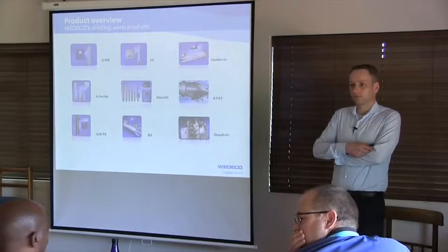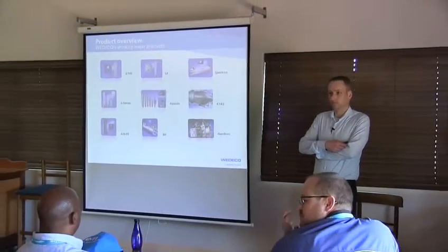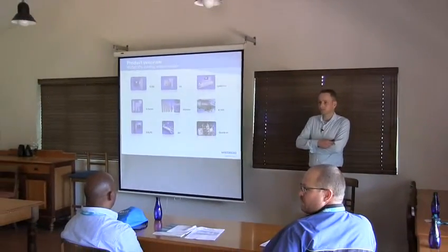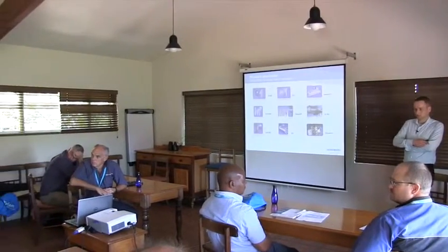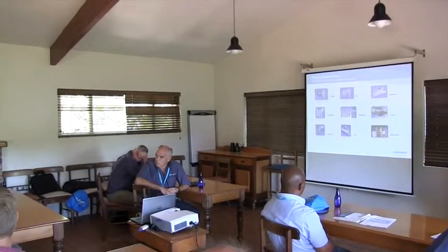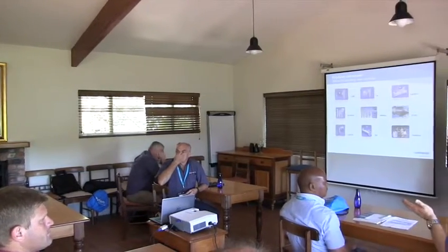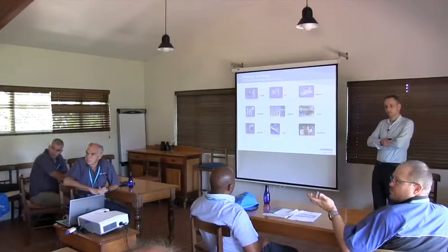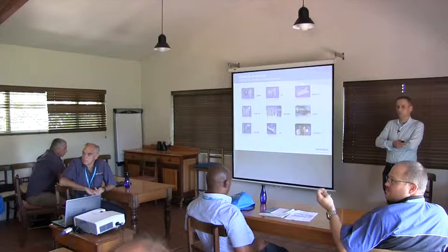How many samples to have? Maybe one, if possible, but if you work on a very big project over a long duration, have one in summer, have one in winter. If you're working on wastewater, with different times of the day where different things are happening, it's useful to have a range. If it's single use, 1 or 2 samples will suffice. If it is a big project, you need a week or 2 weeks of data and possibly multi-seasonal.